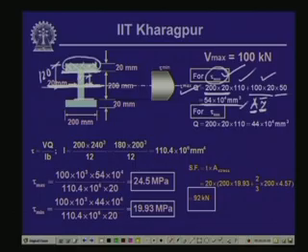Now, for computing the minimum shear stress, tau minimum, at this particular section, the area to be considered for Q is the area above this section, which is this rectangle alone. The area of this rectangle is 200 is the width, 20 is the thickness, and 110 is the distance of its CG from the neutral axis, because 120 is the distance from the neutral axis to the top, minus the CG distance from the top, which is 10, equals 110. So, Q for the top rectangle only is equal to this, which is required for evaluation of the minimum shearing stress.